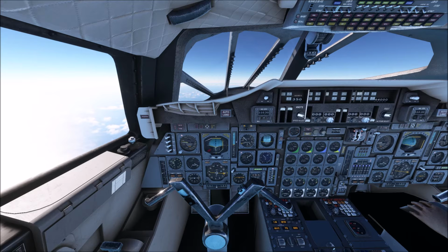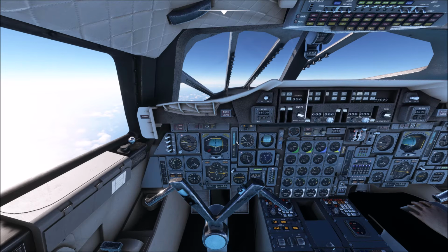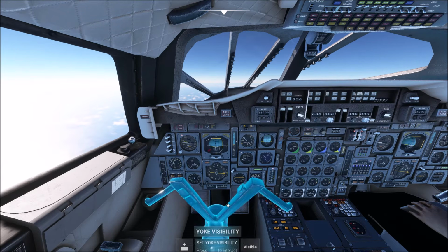And as you can see, it's automated. You know, if you don't want the difficulty or the extra workload of doing it all yourself, obviously you've got to do some jobs, but it really does most of it for you if you want it to. See climb rate now coming right down, going up again now. It was at 600-700 feet a minute, going down again. So it's all being done with the nose. It's just adjusting gradually. You just about see it moving up and down, constantly balancing. It's not doing it with throttle, they're fairly stable. It's all about attitude.